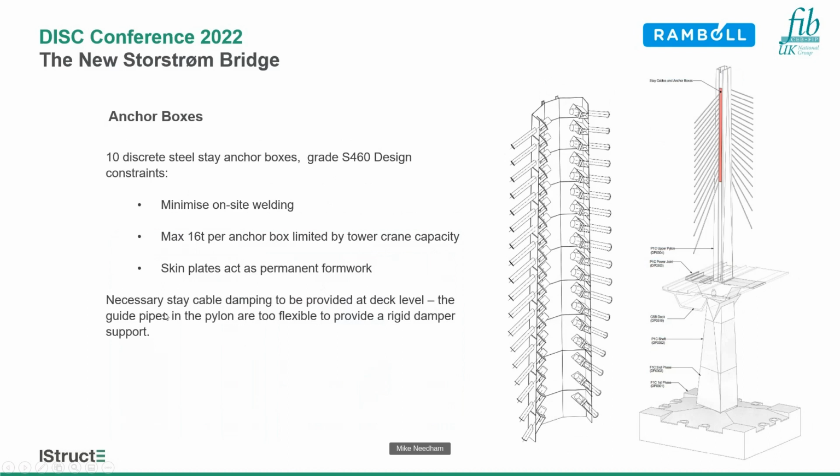A key feature, of course, is the stay cable damping, and that's actually provided at deck level in this case because the guide pipes in the pylon are just too flexible to provide a rigid damper support.